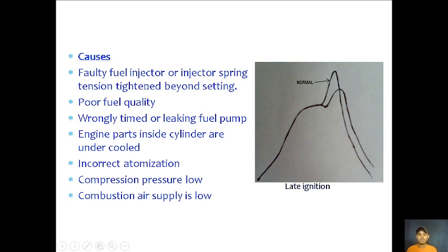So what are the causes? Faulty fuel injector or injector spring tension tightened beyond setting, poor fuel quality, wrongly timed or leaking fuel pump, engine parts inside the cylinder are undercooled, incorrect atomization, compression pressure low, but if you can see, the pressure is normal, so this may not be correct. Combustion air supply is low, but as you can see, the air here is at normal pressure, so maybe this is incorrect. But it is also good to check. Always check.